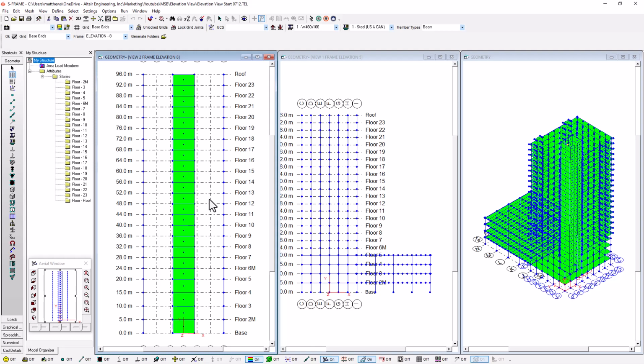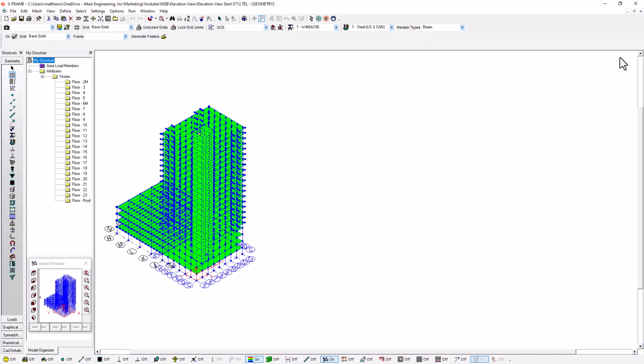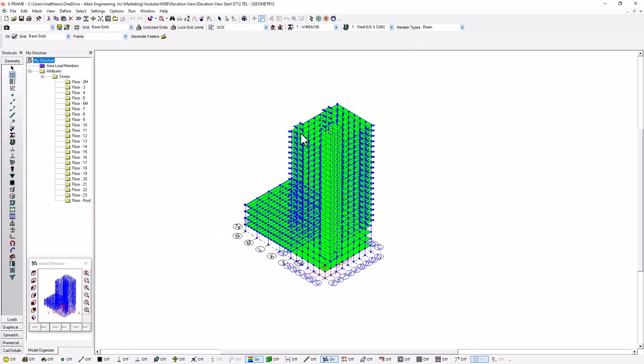Now one of the handy features of this type of elevation view is adding geometry to our model. So I'm just going to actually close some of these views here, and I'll expand the geometry view again. And what I want to do now is look at the podium grid, and specifically grid line N, which is at the end of my podium. So I'm just going to select grid line N, and actually, you know what? It's probably just easier for me to switch to my podium because I have a smaller set to search through. And I can see here elevation N.